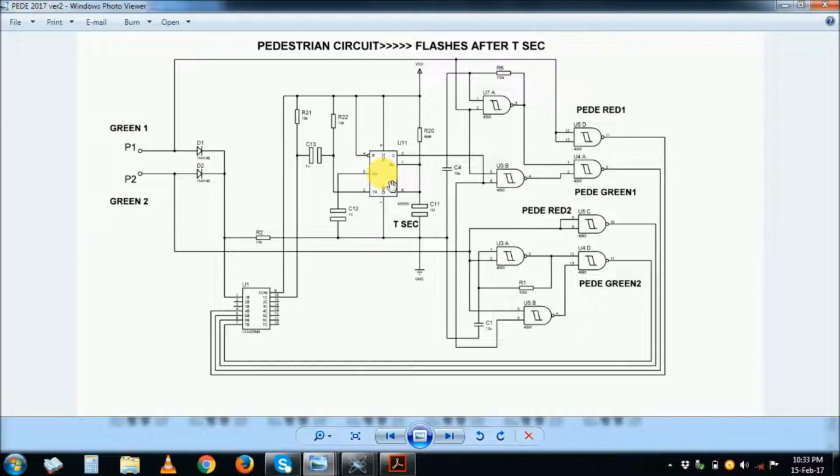The implication of having one single timer is it means the time for flashing is actually the same for both sides, of which normally is not the case usually. The time for flashing is different, because sometimes the green time here is different for each side, so you need another circuit here. So here, as you can see, the diodes here are just an OR gate. Definitely, if you are going to use one timer, use this setup here, or you can use an OR gate if you want, if you have ICs that you would want to put around.